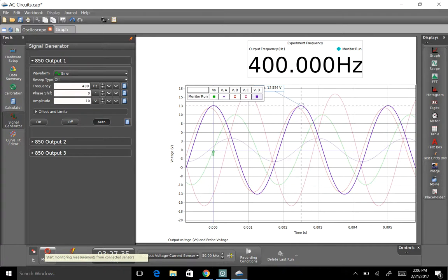At any one time, for instance where this vertical line is, if I add up all of the voltages for each piece, I have to throw out the blue one because that's a combination. But if I add up everything that's not the blue one and not the green one, it needs to add up to the green one, because that's what Kirchhoff's voltage law says. Go around the circle and add up all of the voltages, it has to add up to 0.